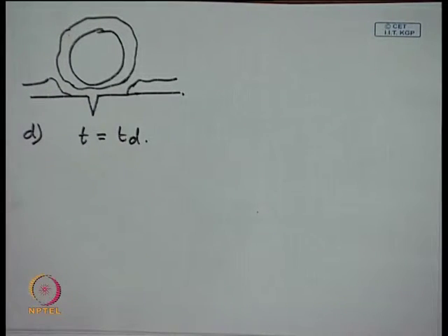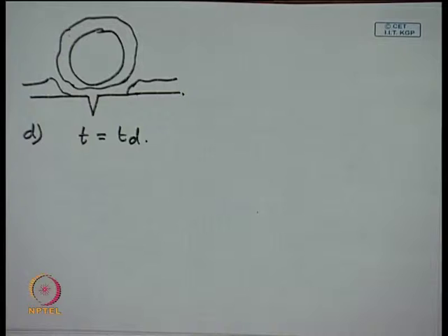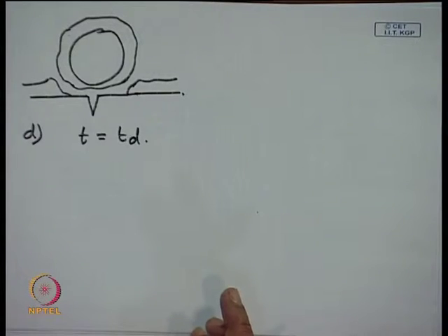Okay. Now, as I have described, these are based on some idealization. Ideally I have told that it is inertia controlled and then it will be controlled by the heat transfer process, but actually it need not be so. Depending on the working condition, either it can be inertia controlled or it can be controlled by the heat transfer process, or in other words the inertia controlled process could be very small. Mainly the bubble growth is dependent on the heat transfer control process.